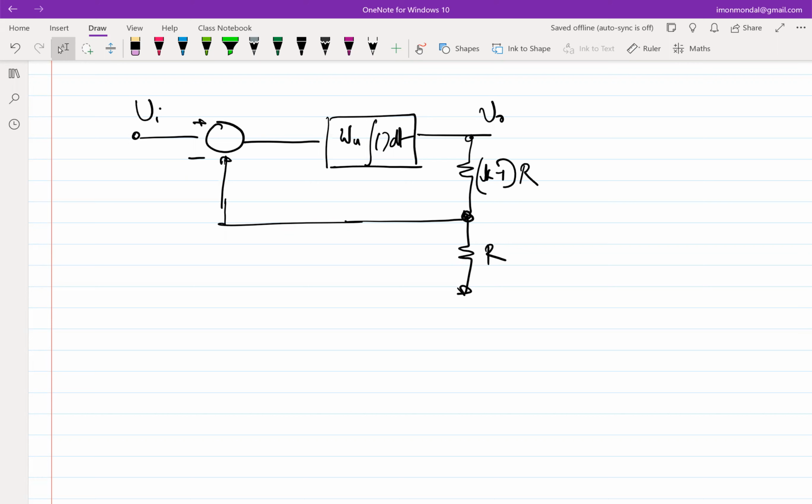And as long as your loop is in negative feedback, the error will go to 0 only when you wait for infinite time, which in other parlance means that since the integrator has infinite loop gain at 0 frequency, the integrator will only get satisfied when its input is essentially 0.